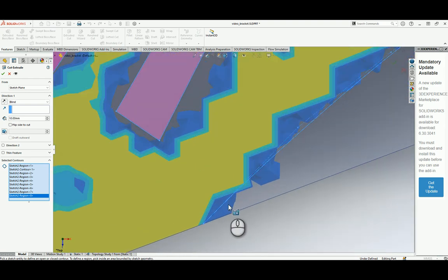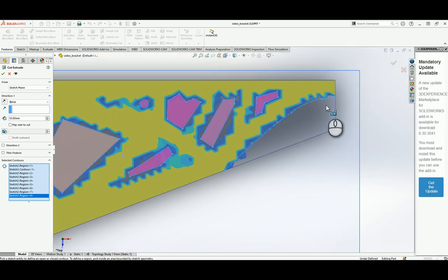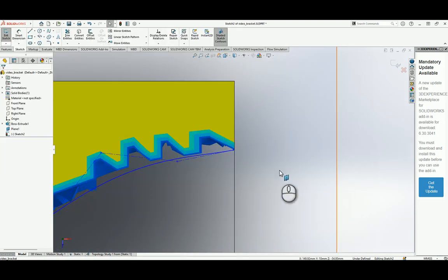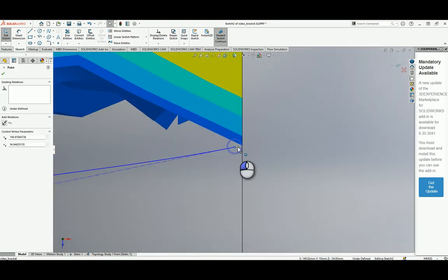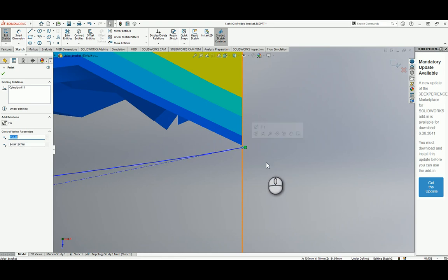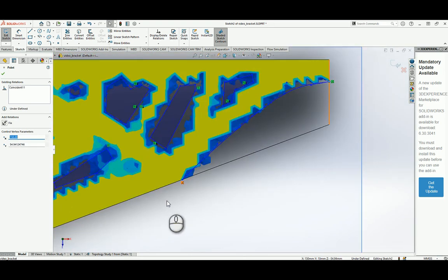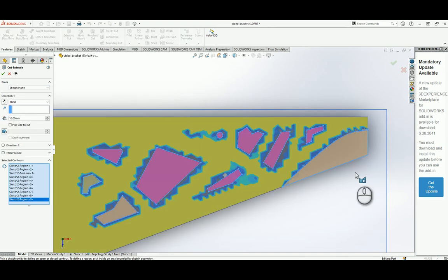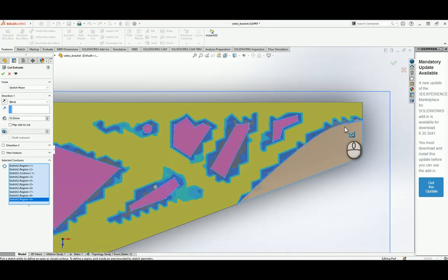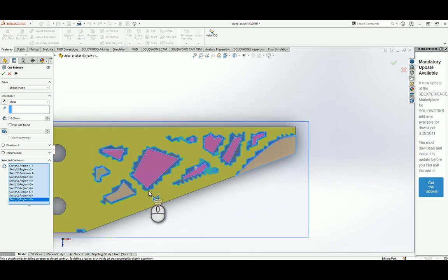Right, so this spline is not creating a closed profile, so we have to go back into the sketch and create a closed loop here. When you zoom in, you realize that the point was not on the line. You can just drag it and ensure that it's on the line, coincident with the line. Ensure that the same constraint is here. Good. So now it's supposed to work. You can see it was able to be selected now.